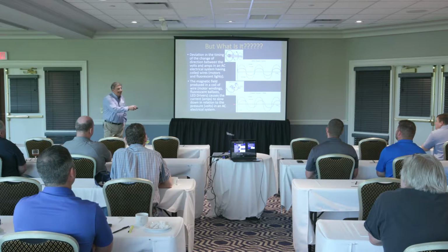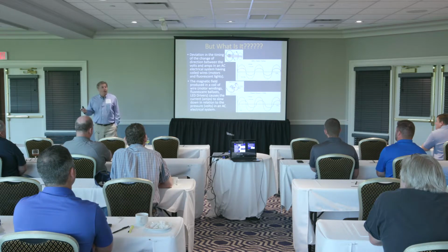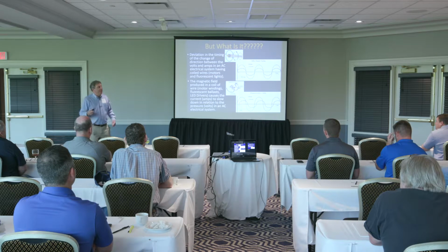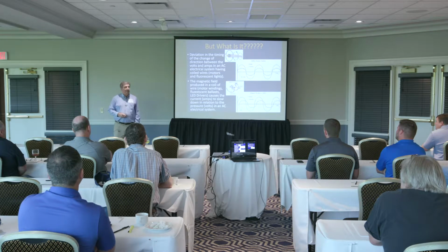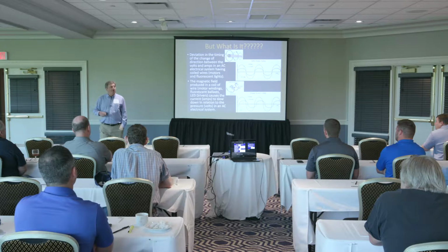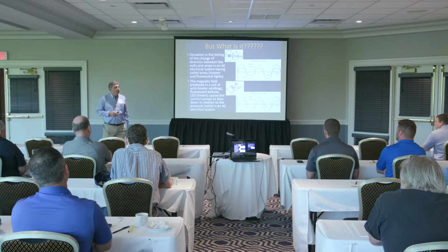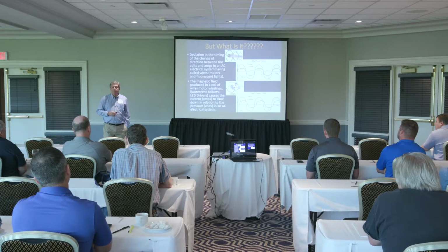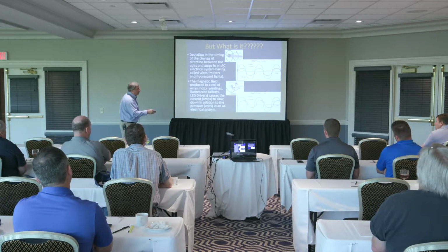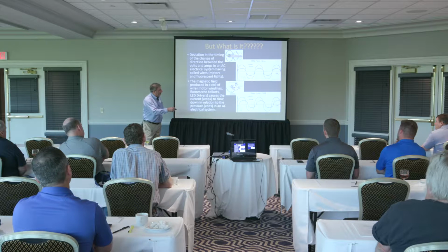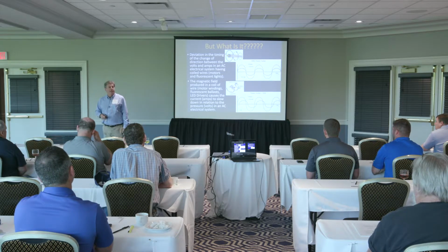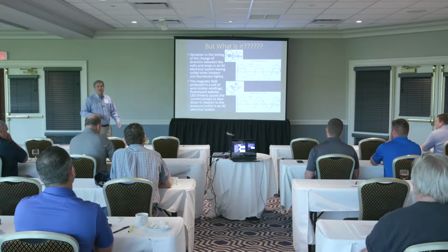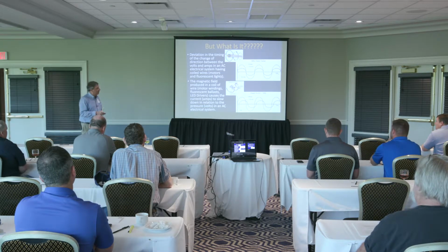So if this lag, which is really my power factor now, becomes too big, things get worse and worse and worse, and the utility's burning fuel at the generating plant to put amps on the system, causing a voltage drop that are really just taking up space out there. So the more low power factor equipment we put on the system, the bigger this lag of the amps behind the volts gets. That's what power factor is. It's caused by those things that have magnetic coils and electronics in your facility.